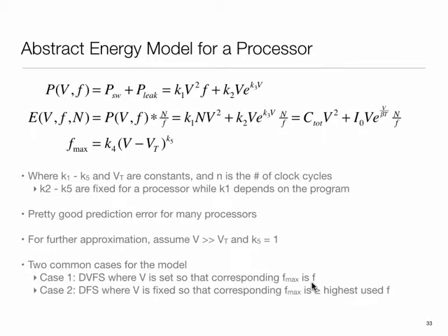It depends upon, for example, how hot it is right now. It depends upon what that particular chip is behaving like. I may buy 100 identical chips, and their Fmax for a given voltage would be slightly different. Then you also have issues like I may tell the system to set the voltage to 5 volt, but in one case it may set it to 5 volt, and in another it might be 4.95, because there are variations in the power supply itself. So the upshot of all of that is that it's not easy to figure out what Fmax is.